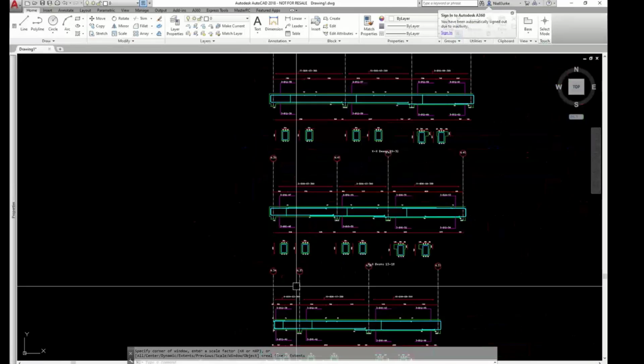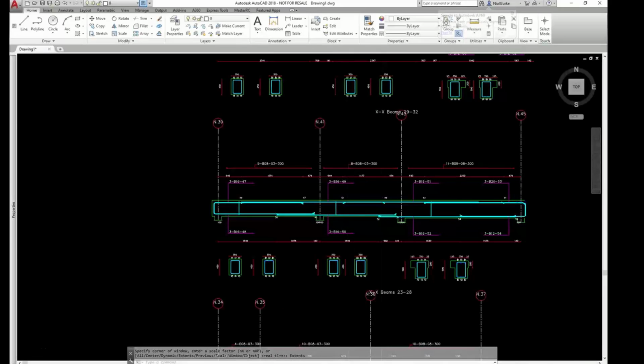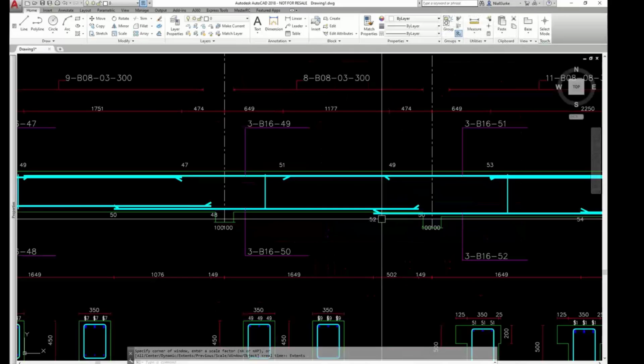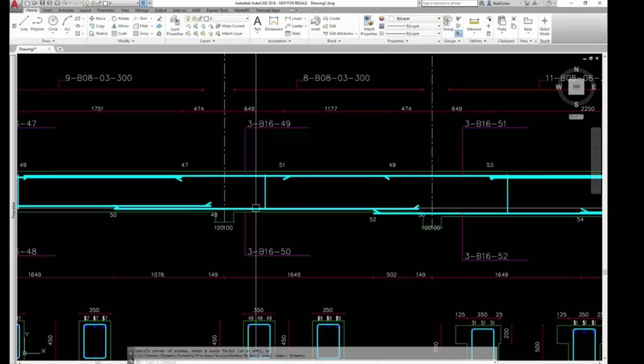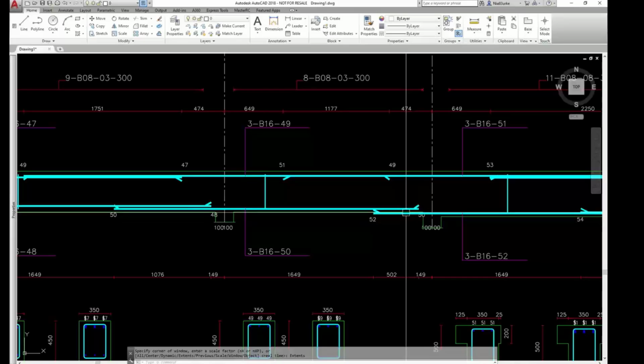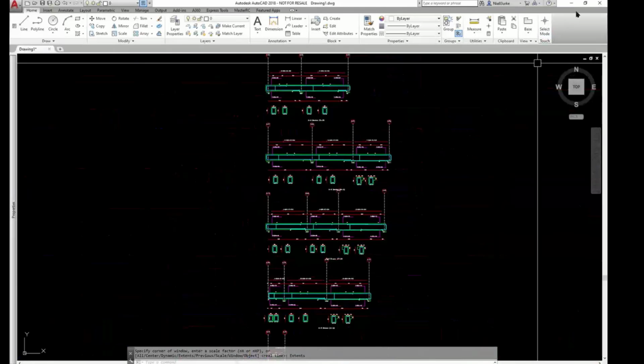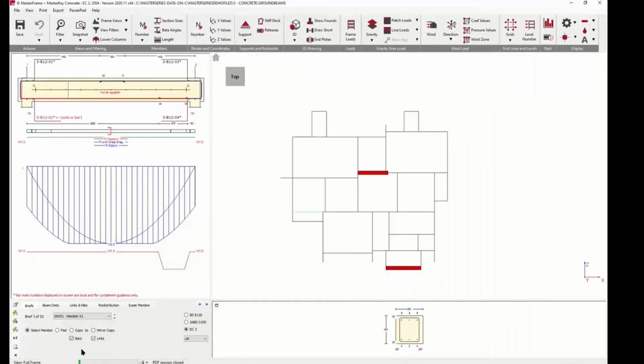slower. So there's my reinforcement and all detailed, and there's a little jump in depth of slabs here, and it's reinforcing that with the jump in the slab between the two levels, and everything is all good and kosher. To mirror that, we can also print a schedule of all that rebar.